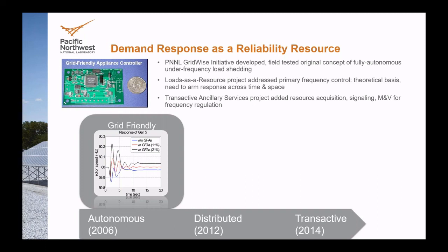So if the power system is overloaded, this little device can basically turn off non-essential appliances, something like your dryer, maybe the heating coils disabled, or if your refrigerator is doing a defrost cycle, maybe turning that off for a moment, basically alleviating the load on the grid so the transmission side can recover, get back up to a stable operating point, and prevent either a blackout or a brownout, all via the load.